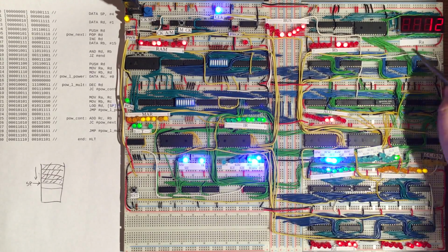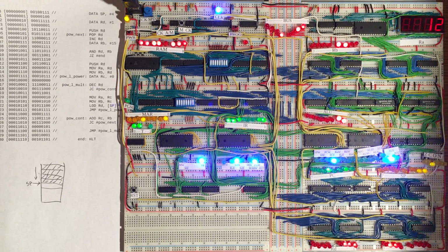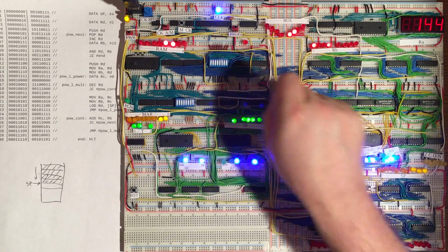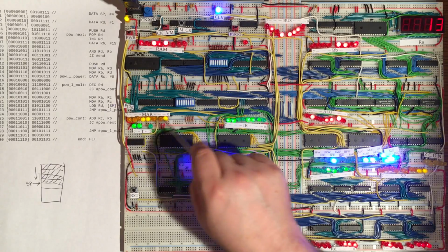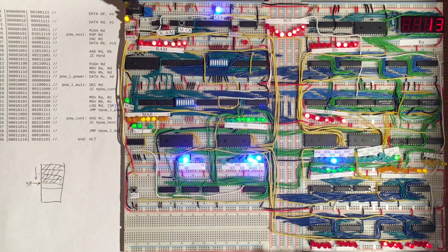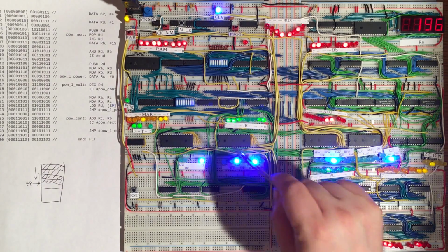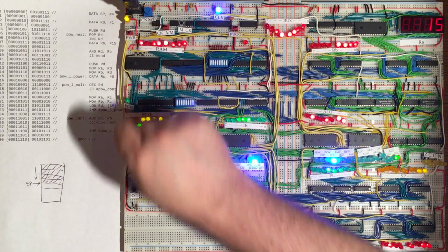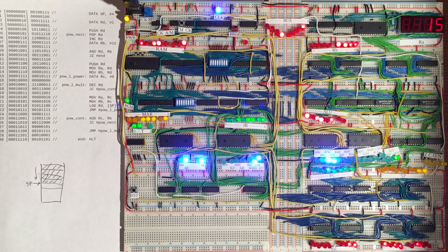And one of the registers has a more complex decimal display. We of course have a RAM module here which uses addresses and then actual data. And in fact we split our RAM into two parts, into program and data memory. We have an instruction register here which we load based on the programs which we can write into program memory.